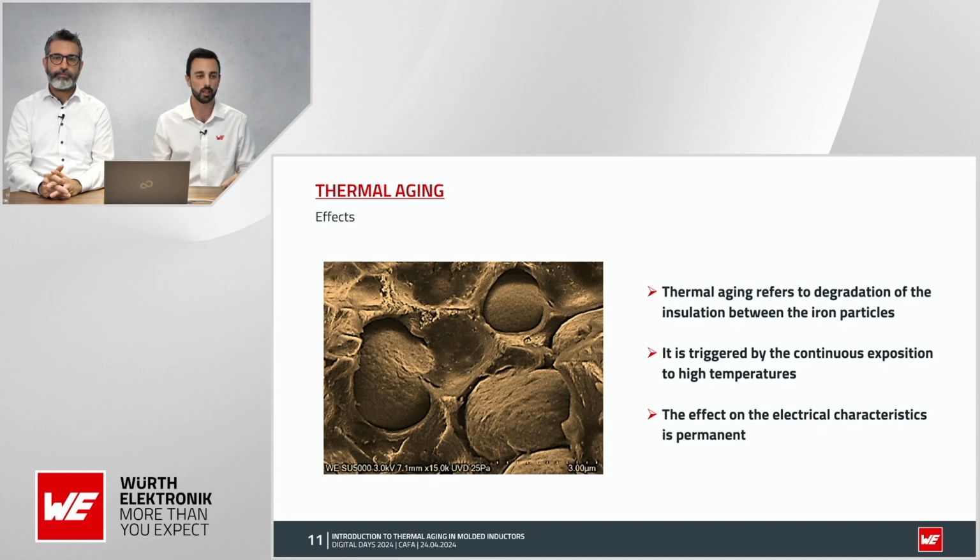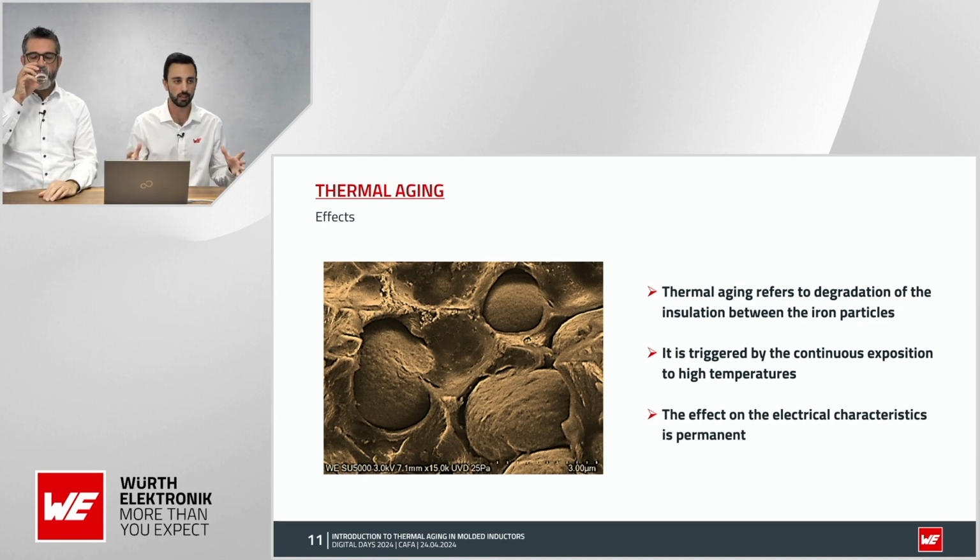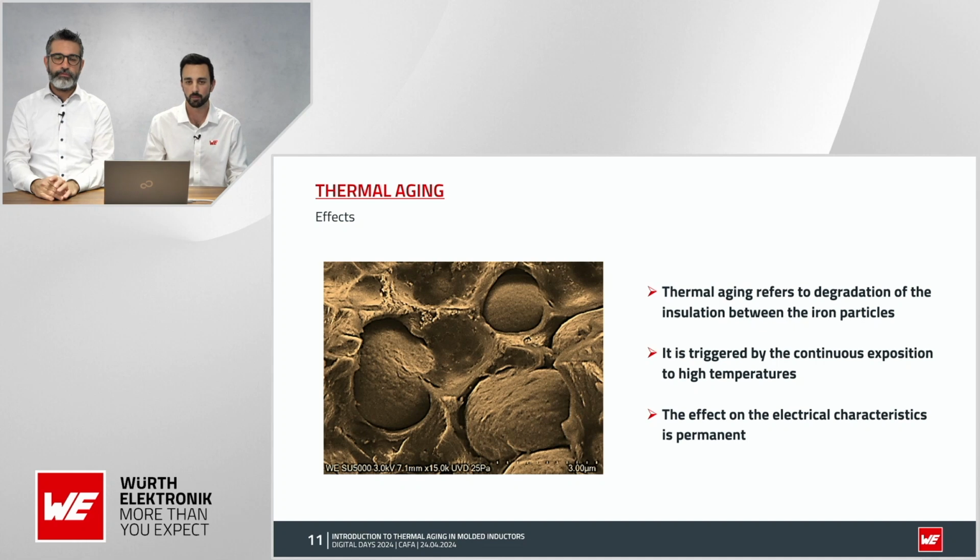The main effect, related to the explanation we have just made about the eddy current losses, is that the losses in the core will increase over time, and the performance and efficiency of your system will go down. The losses in the part will go up. Also, the operating temperature will go up because of this effect, and you can face problems of thermal runaway.